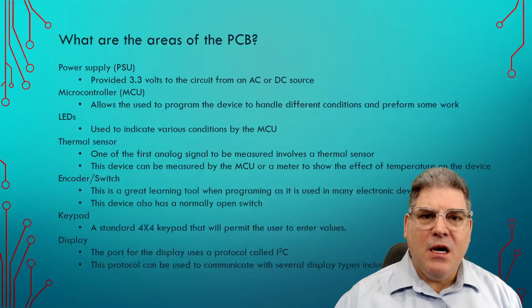Some LEDs. Now, I think that you've already done like a Christmas tree or a stoplight or something like that. LEDs are ubiquitous. They're everywhere. And I usually have one on one of my circuit boards somewhere that's tied to a pin that allows me to do troubleshooting, at least in the first iteration or second iteration, and later can go away if I don't need it as a user interface.